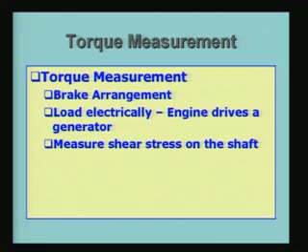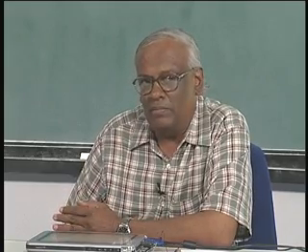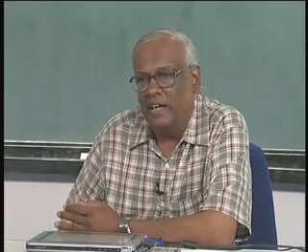We can also measure the torque by allowing the engine to drive a generator, and the generator is generating electrical current with a certain voltage. Now, I can load the generator by connecting it to a set of resistances which will dissipate the energy in the form of heat. So, I convert the mechanical power to electrical power, and the electrical power is dissipated,